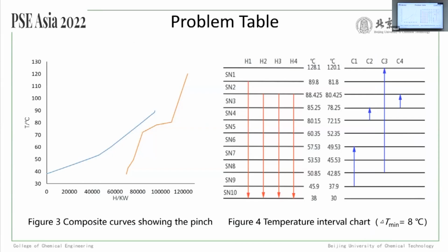As a heat exchange network consists of multiple streams and phase transition, the pinch point is hard to specify by horizontally moving the temperature enthalpy curve in the enthalpy diagram. The problem table method is therefore adopted to obtain the pinch points, where the amounts of cold and hot utilities can be calculated more accurately.